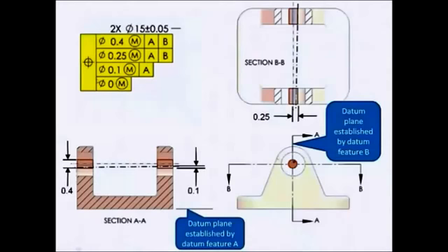Remember that the lowest segment of a composite tolerance, in fact, any of these three segments, main purpose is to control the holes better to each other. If I repeat the datums, they're there for orientation only. So this last one is the tightest refinement on controlling the location of the holes to one another. Keep them in line.